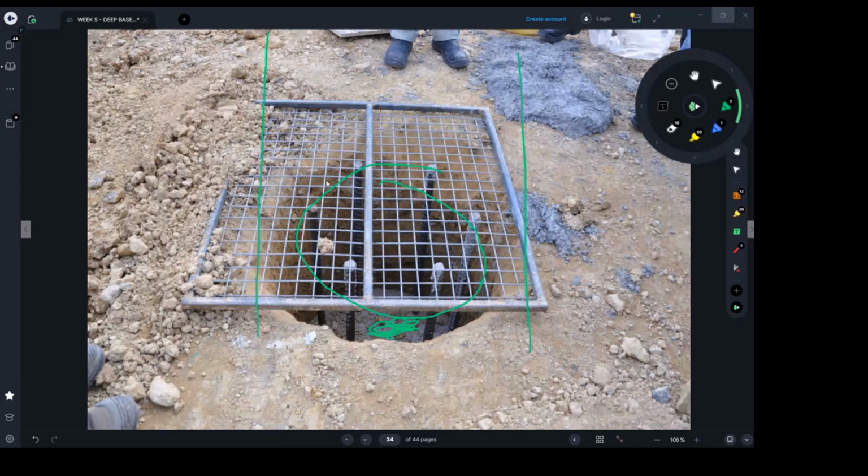They needed to jackhammer each pile, and jackhammering was a problem because you may crack the whole pile. The engineer's advice there was that you have to carefully saw cut them piece by piece. You have to saw cut, remove that gray concrete slowly, and expose the steel. Nobody knows what they actually did.